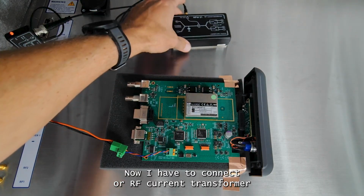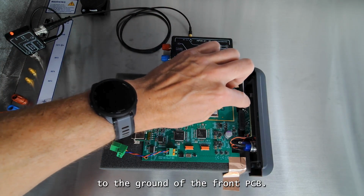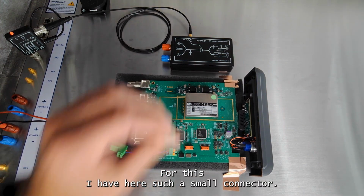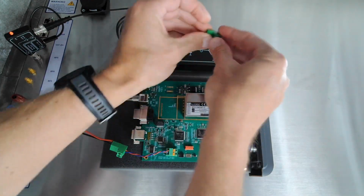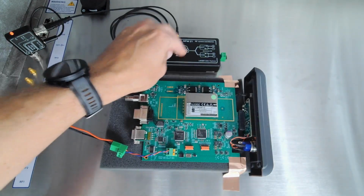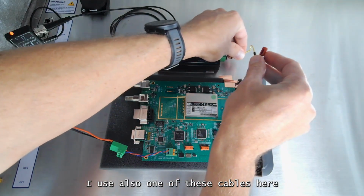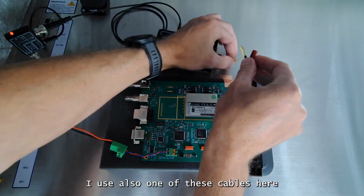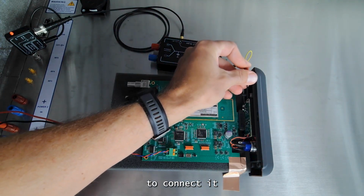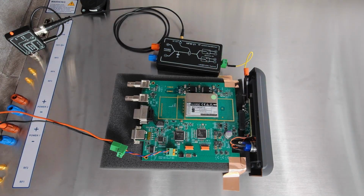Now I have to connect our RF current transformer to the ground of the front PCB. For this I have here such a small connector. This I bring here also in the common mode input. And now I use also one of these cables here to connect it to the ground of the front panel board.